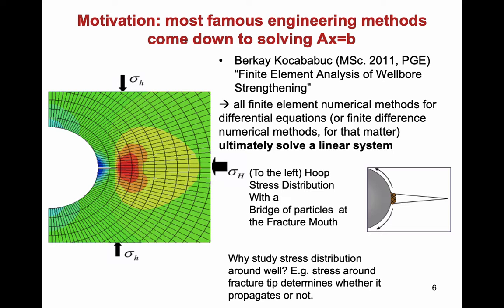What happens in subsurface, and you're going to get to that in geomechanics and drilling, is that most of the time, pretty much all the time, you have uneven stresses acting in different directions. And stress field, which you might or might not know now from statics, you can describe by 3 major stresses in 3 orthogonal directions, right? And vertical is most often one of those directions, simply because that's how you stack things up and weight in the subsurface. And then in horizontal direction, I have 2 other stresses. Here they're labeled sigma lowercase h and sigma uppercase h. Okay? So one of them, this uppercase h, is squeezing a little more than the other.